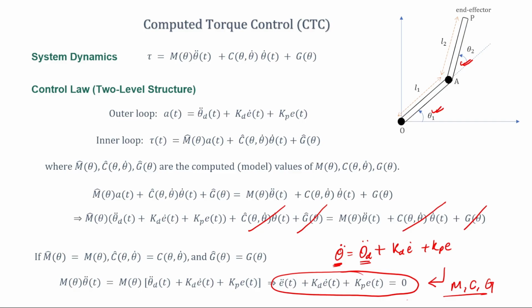One is an outer loop controller and the other is an inner loop controller. It will be something like this. So you will have theta d, you have theta, and then you have this control loop. This is a PD controller, and then the output of this is AT. This goes into the next controller, which is another type of controller, PD controller say, and this is how the loop is like.